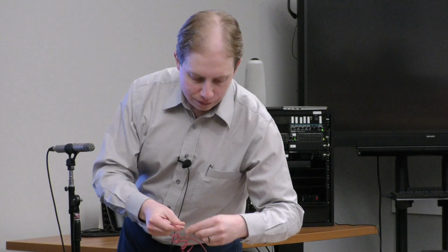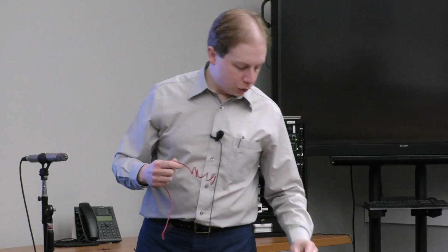Whereas this right here is a wire-wound resistor. This is called wire-wound because inside of this ceramic housing literally is a piece of resistive wire that's wound round and round some kind of a form. Well, this starts to look like this or this. That coil of wire is an inductor. In fact, you can make inductors, practical inductors, by literally coiling a piece of wire. And so these wire-wound resistors have very high inductance. But that's usually not why you select them. You select this for its resistive properties. But as a side effect, you get inductance.